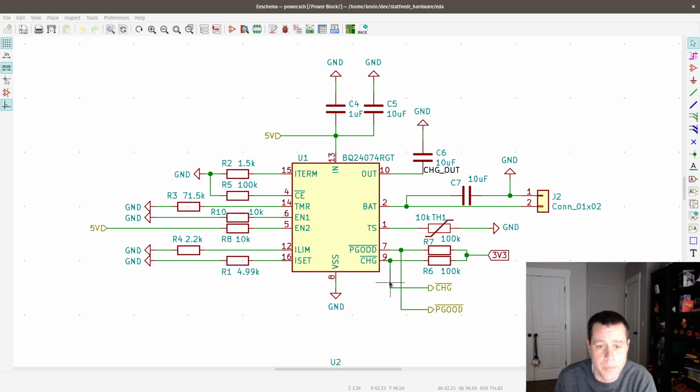Let's talk a little bit about the PMIC some more. You connect the battery, and you've got an input supply. This input comes from the micro USB port. Again, this chip is responsible for deciding which of these to use to power the load. It will favor the input over the battery while the input is connected so that it can charge the battery.